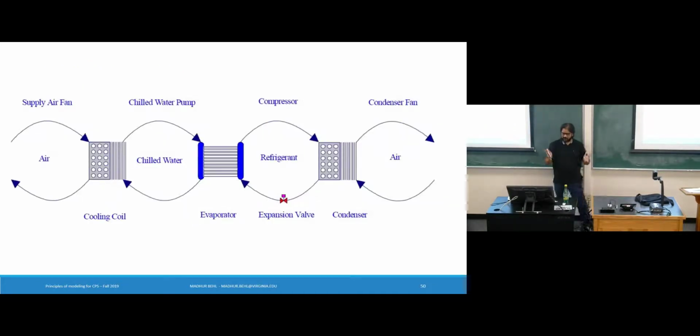So this is a good summary of these different loops. At the zone level, we had the air handling unit, which circulates cool air into the zones. This arrow denotes the return air coming from the zones. It has to be cooled back down to 42 degrees Fahrenheit, so that exchange takes place with the heat exchanger. How does this heat exchanger work? We are continuously supplying chilled water into the exchanger. It picks up the heat, and hot water comes out of the heat exchanger.